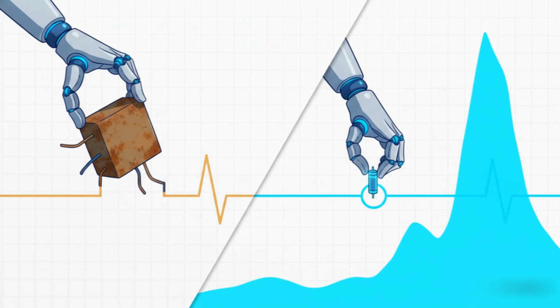This one is set up to act like a perfect current source. We call this an active load, and it gives you an insanely high effective resistance. So you get tons of voltage gain, but it only takes up the space of one little transistor.